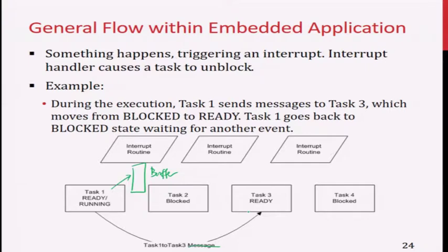Now in multi-threaded, you must think of all the different functions that I need to fulfill. How many tasks do I need, and how will they communicate? Each task has an objective, but at the same time there is a way for me to synchronize. So I can say that task 3 will only run after task 1 has completed a certain part of the activity.